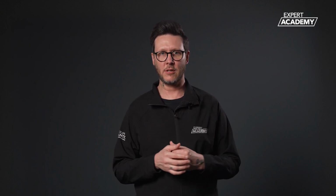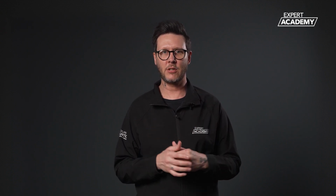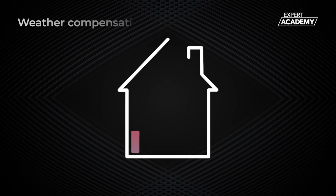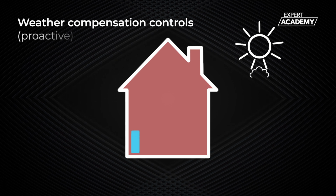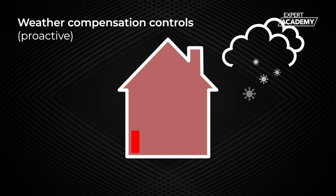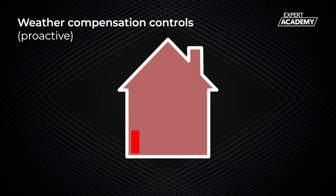This highlights the benefit of weather compensating controls, as adjusting the heat delivered to meet the heat demand helps reduce unnecessary energy usage and provide a more stable temperature within the home. Weather compensation controls adopt a proactive approach to heating buildings, continually adjusting the heat source output dependent upon the current weather conditions, while still maintaining a consistent room temperature.